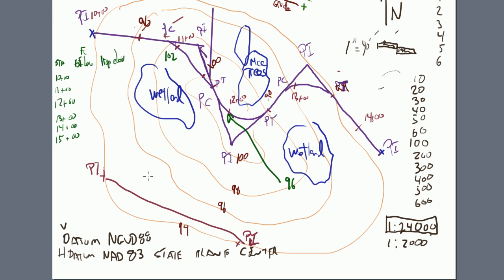Alright, the last thing that you need, and was probably the first thing you needed to do, and we'll talk about where we're going to put this, but way down over here on the plane, we should have come up with some sort of sketch which shows our proposed cross-section, our typical cross-section. That's going to be called an assembly in Civil 3D, but something that shows, like here, this is 10 feet. It should show your center line or reference line, and this is 1 to 1, horizontal to vertical. You know, H to V, horizontal to vertical, is 1 to 1. That is the place that follows along this alignment here.